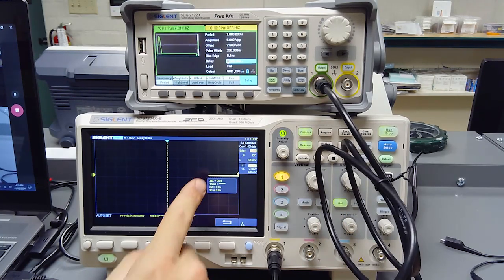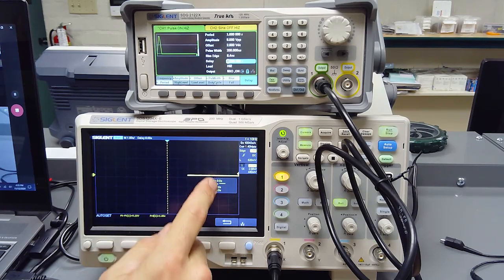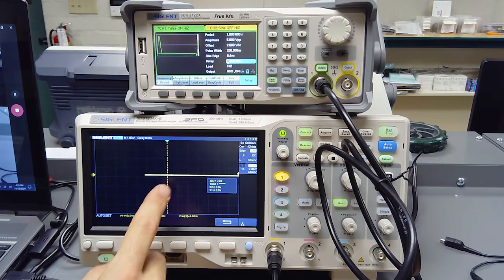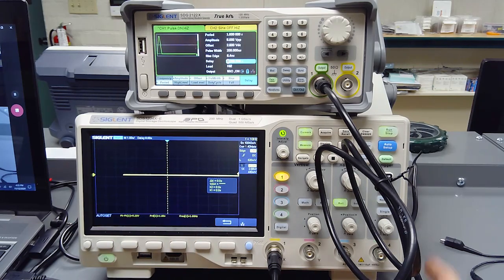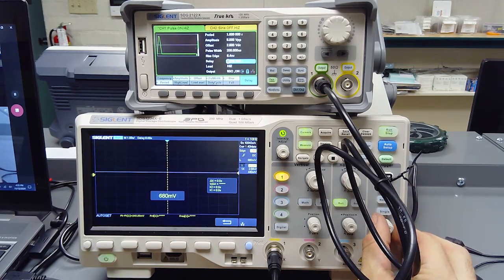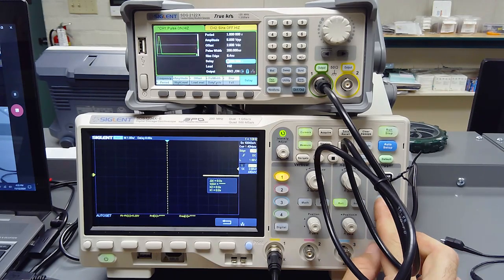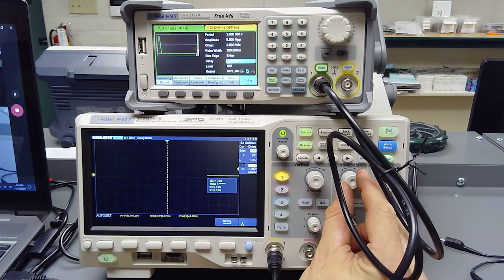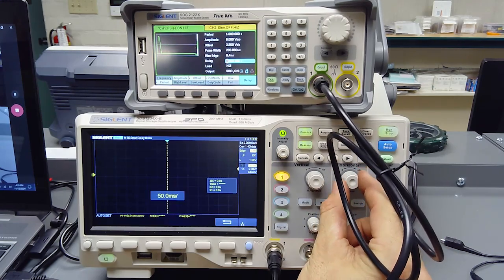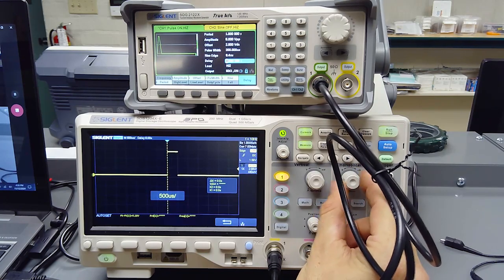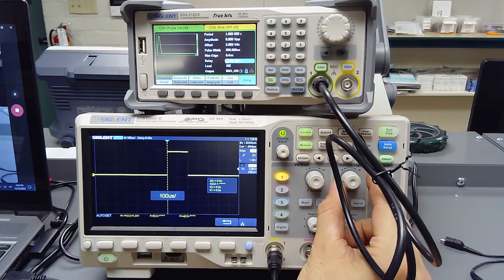So now we can see there's little spikes every second apart. But I want to trigger on that so I can look at it closer up. So first, let me make sure my trigger level is good. So we're going to set it to right around there. And I'm going to say normal. And I'm going to zoom in quite a bit. And then I'm going to see if I caught that. There it is. So that's the square wave pulse.